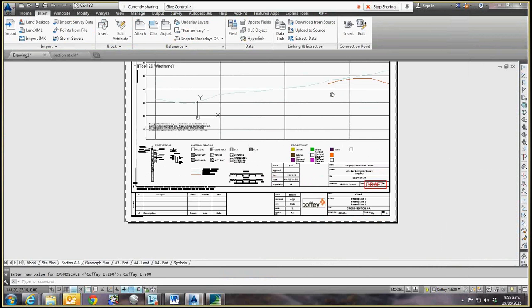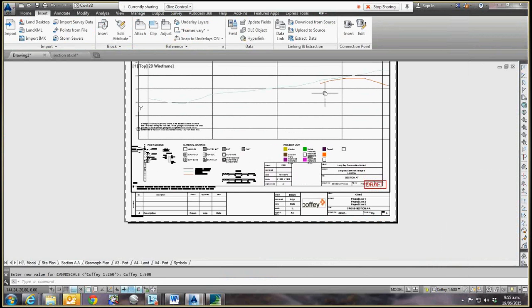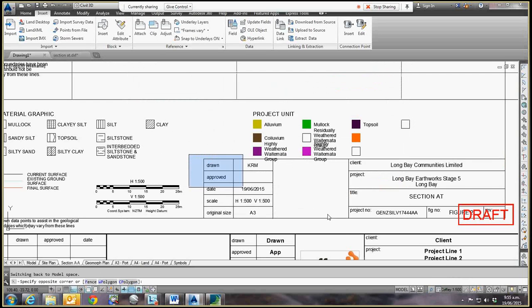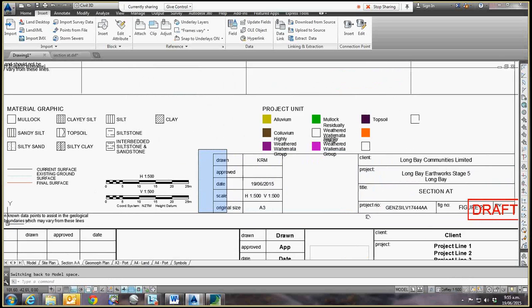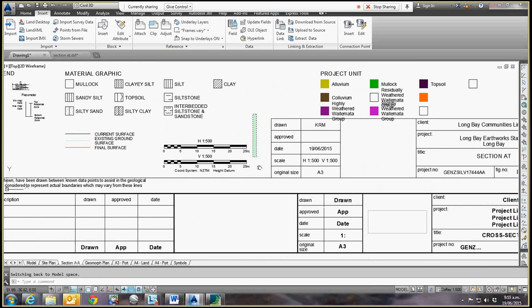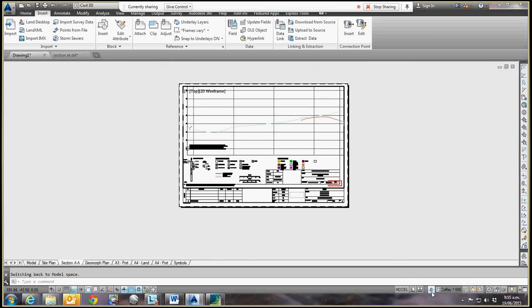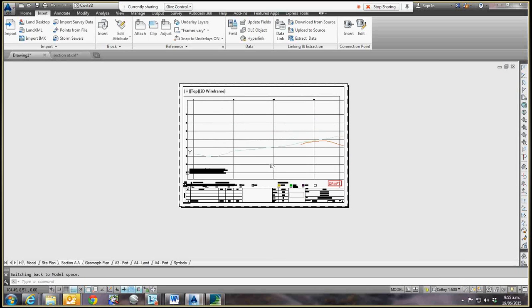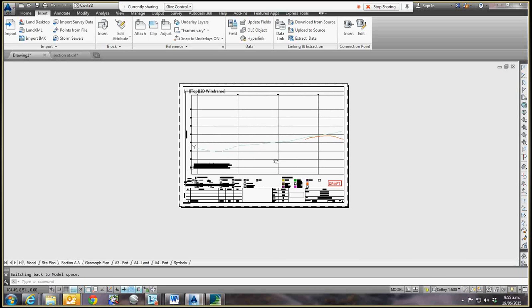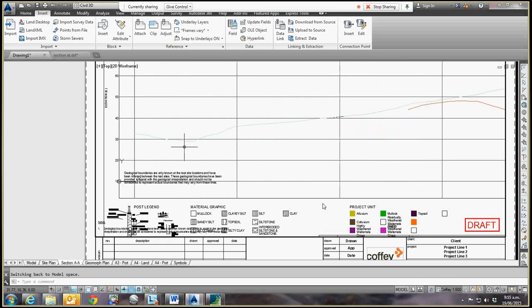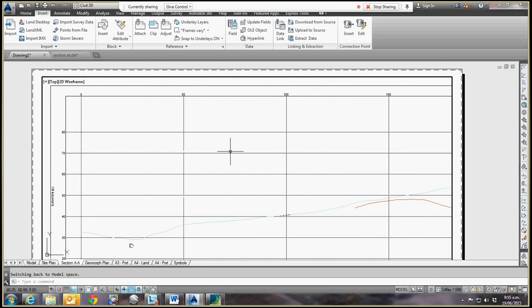Beautiful. So it has its own title block in here. I usually get rid of this stuff. I usually don't want that stuff because I have my own down below. And then we usually stick our scale bar in paper space in this tab. But some of the symbols and stuff you can leave in the legend. So I will pan this down until it's about like that. And now everything's the right scale. It fits nicely on my drawing.